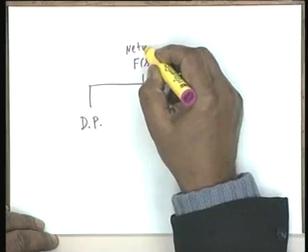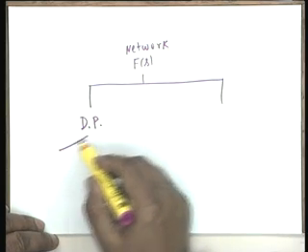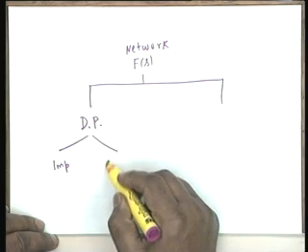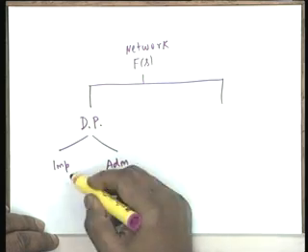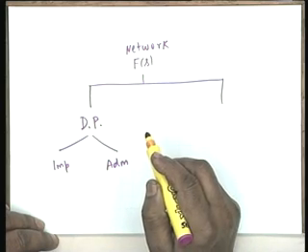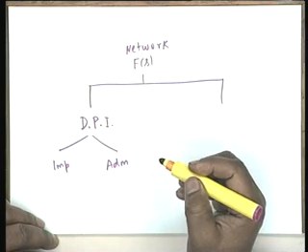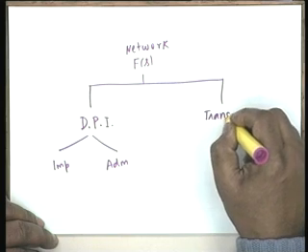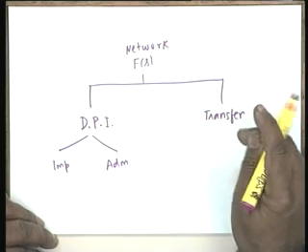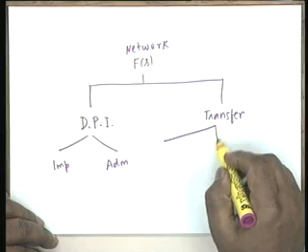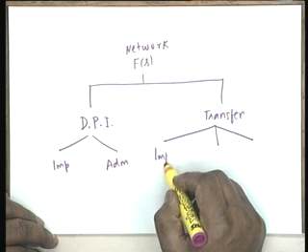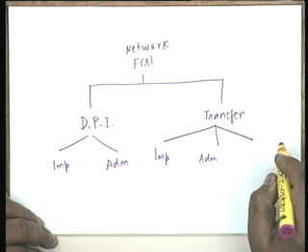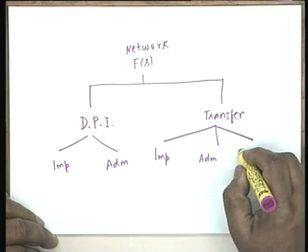So, the network function f of s can be either driving point, and if it is driving point, it could be either impedance or admittance, and both of them are combined into a single term called immittance, and we call this DPI, driving point immittance function, or it could be a transfer function, that is, if the excitation and response are at different ports. The transfer function could be either an impedance or an admittance or dimensionless.